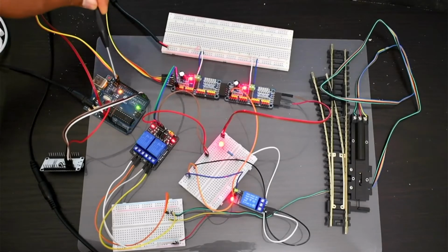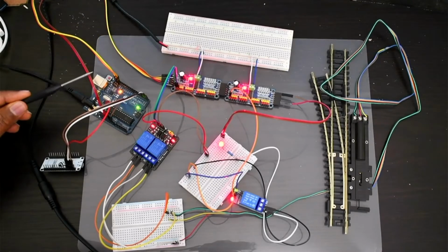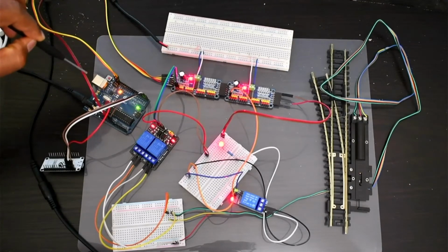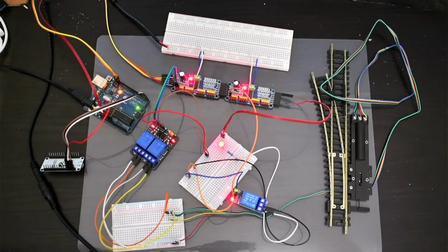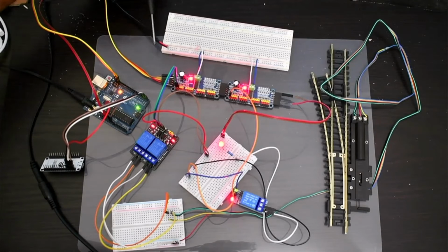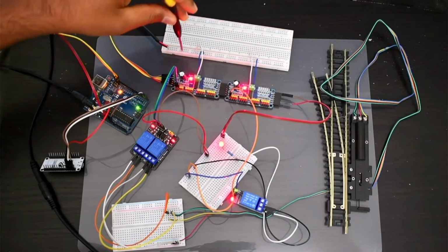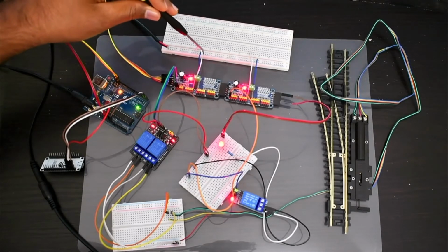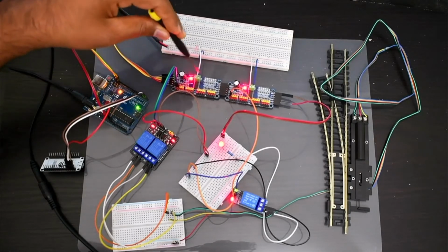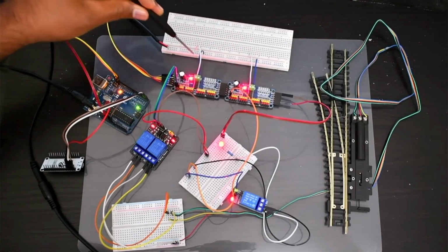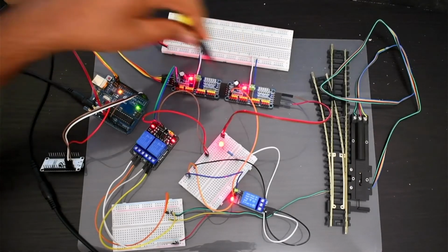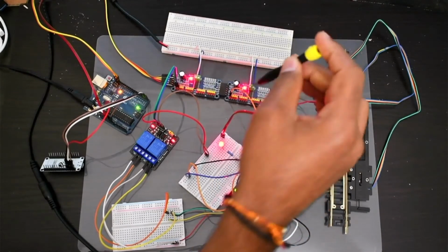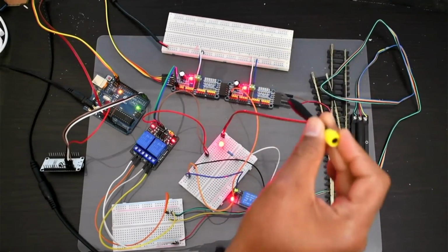And for the PCA9685 board, from the Uno we have taken yellow as SCL and SDA, and orange is the SCL line going from the Uno to there. This red one is 5 volt, and brown is GND, which is going to the first PCA9685 board. Here you can see there is an external 5 volt power supply coming to this breadboard. From this breadboard we are taking the 5 volt external power supply for the first board and second board. The blue one is GND, and the white one is 5 volt, and GND, which is going to the first and second board. So what I did, I bought this connector separately and soldered it here at the end,